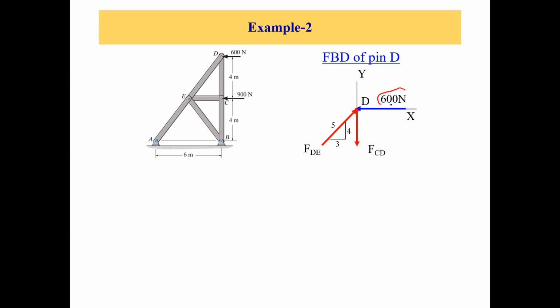Then we have two member forces, FDE and FDC. FCD they have taken in the tensile direction, but FDE in the compressive direction, due to this 600 newtons load.